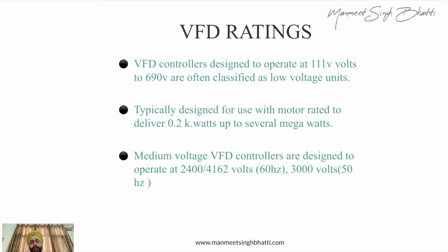Now coming to more details on VFDs: VFD controllers are designed to operate from 100 volts, 110 volts to 690 volts. These are the basic ones, so we call them low voltage. With low voltage, the motors are easily available, and you can manage it in your plant. You don't need any specially trained people to manage it. So that is what you can do.